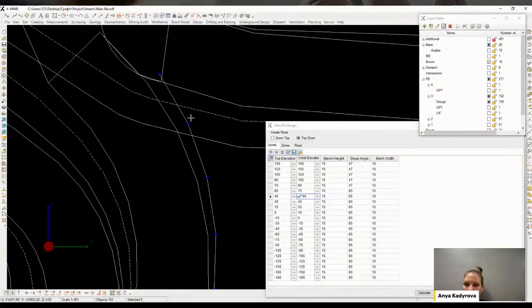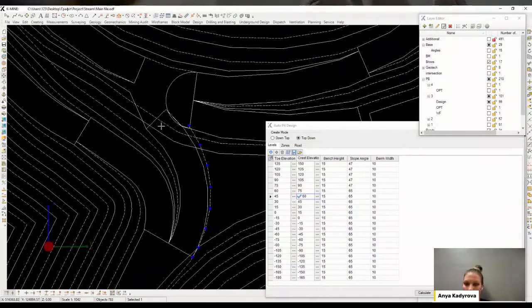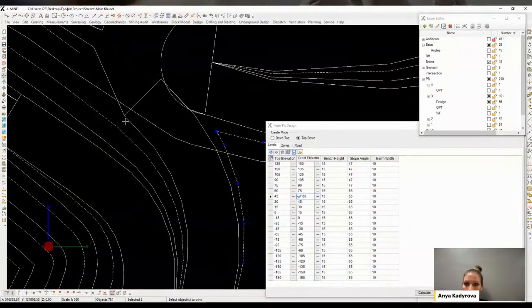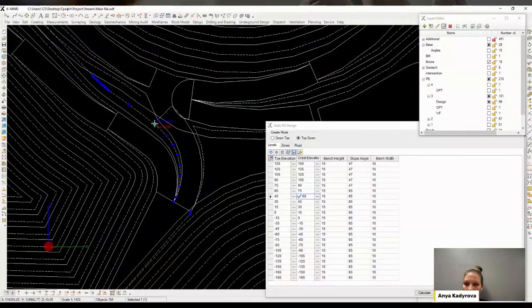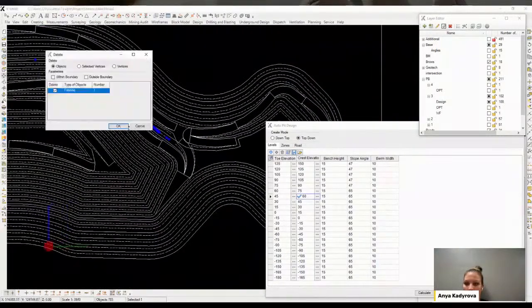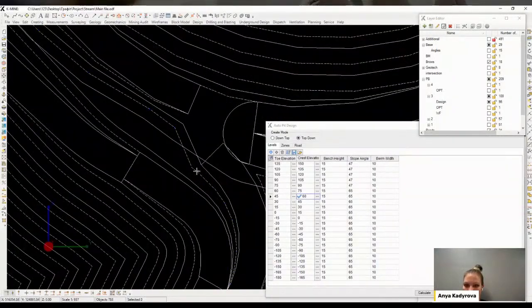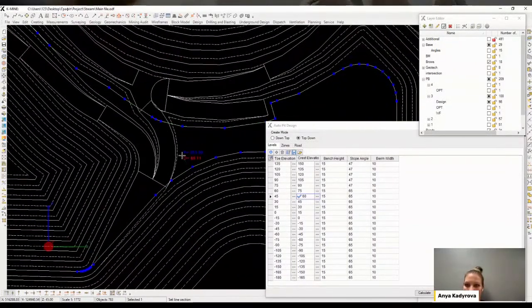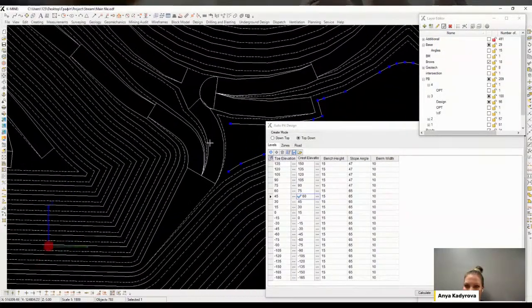So let's prepare the next edge in order to use it as a reference and copy a part of the pit that will not be modified for its further use. Let's return to the construction and define the prepared upper edge as a reference to the corresponding horizon and perform the construction with virtual lines. Then we add the road at the junction to the previous section so as to get a continuation. And let's stop the construction in a narrow place, accept the construction and remove the extra edges.